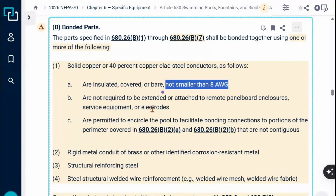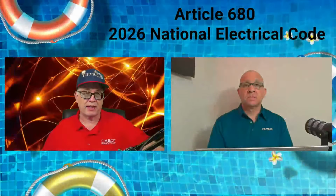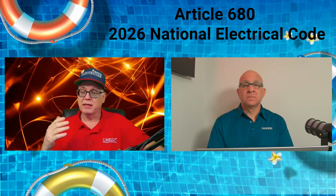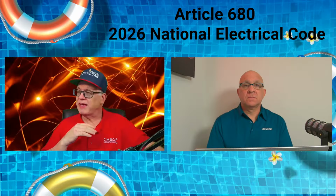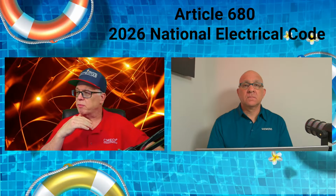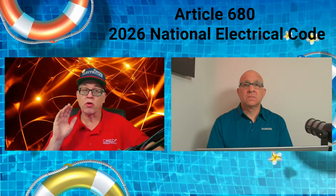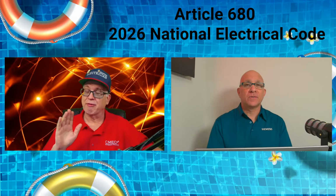So first of all, it's pretty clear in the code that this is not an electrode. We're not using this as an electrode. It may look very similar to a concrete-encased electrode, but if it is rebar in concrete, that's not what it is. We don't take this bonding of these parts all the way back to a remote distribution panel, the pool panel. We don't have to take this, although it's not saying we can't. That's correct, we're not required to do it.